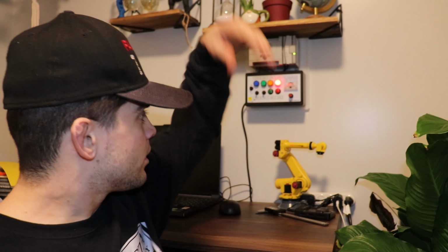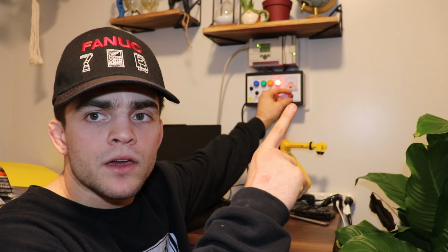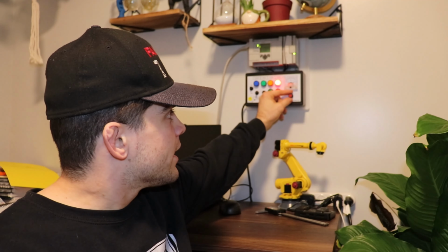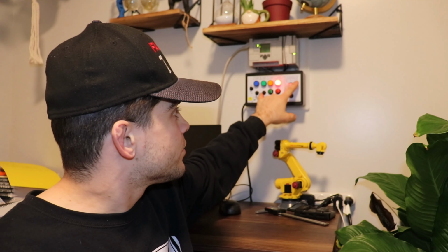In particular, we have a little potentiometer knob on here, which should be on your left. And then we also have an actual voltage output here from 0 to 10. This is going to represent the actual voltage. So instead of scaling 4 to 20, which would be a current scaling, we're actually going to scale it from 0 to 10 volts. With that being said, we're going to hop into the actual software and start programming this, and let's get this scaled for today's video.